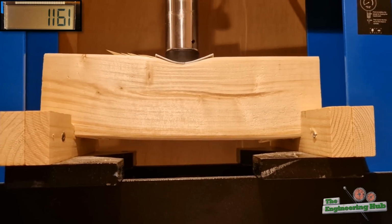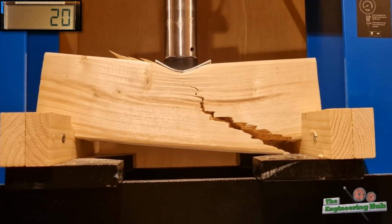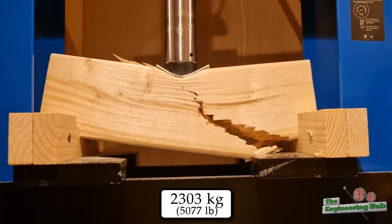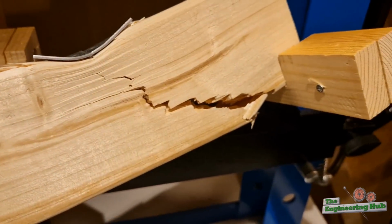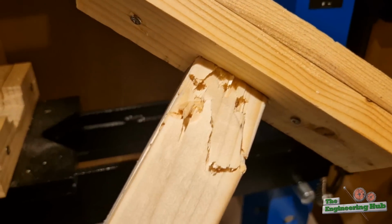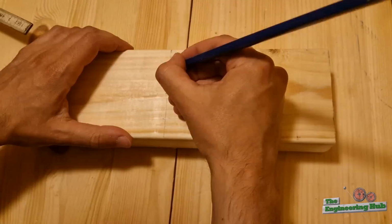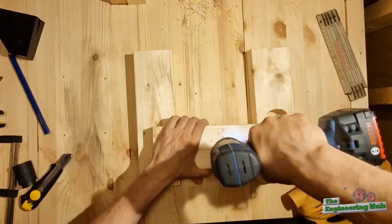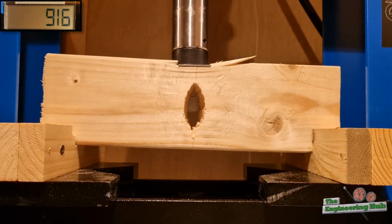A 30 cm long European-sized 2x4 can carry more than 2300 kilos, or about 5,000 pounds, of concentrated load. Of course, this number becomes much smaller for longer boards, but how does the capacity change when we drill a hole in it? Say we make an elliptical hole with the major diameter being half of the beam's depth. Let's see what happens.